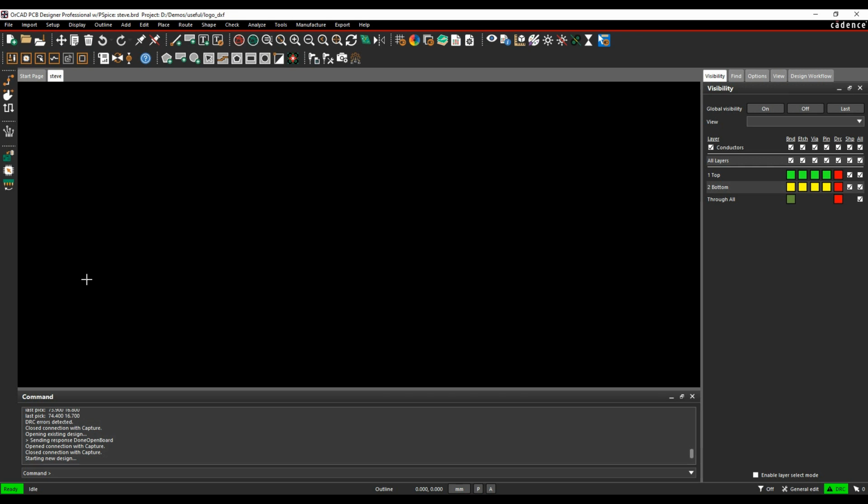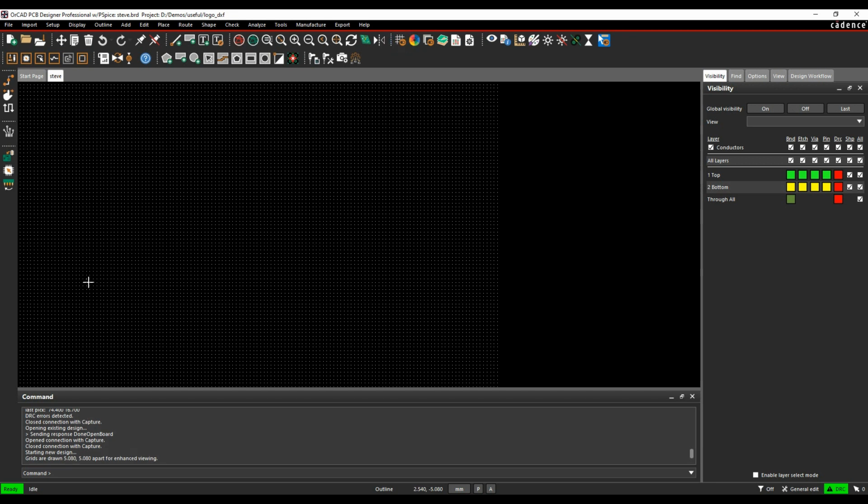So obviously we work on 0,0, that ties in with the DXF file from AutoCAD or any of the other MCAD tools. So you need to make sure from a 0,0 point of view you've got enough space to put this in. So if I put on the grids, for example, you'll see obviously this is 0,0. I need to make sure I've got enough value on the minus part of the 0,0 just to make sure I can import the stuff if that's the way that the DXF file has been generated.